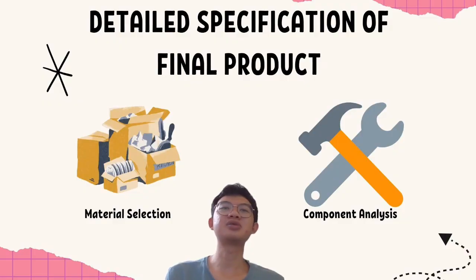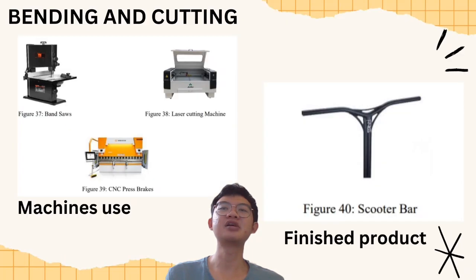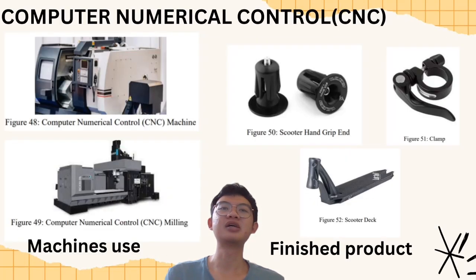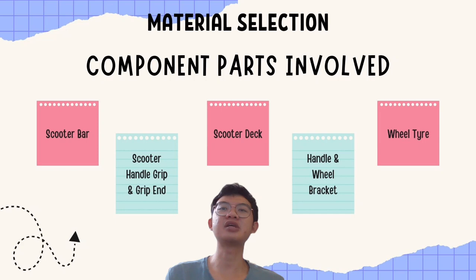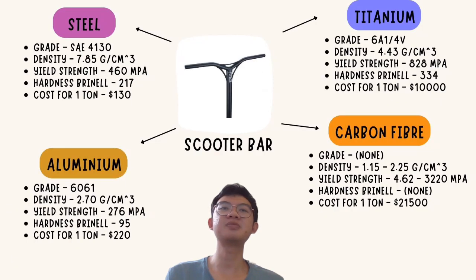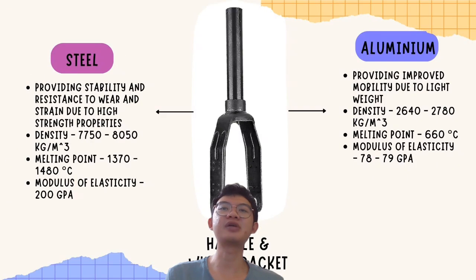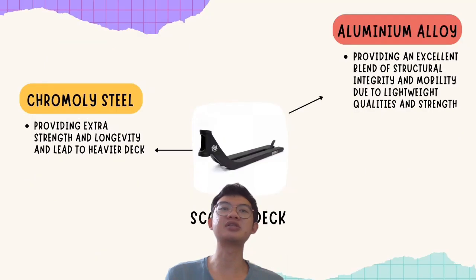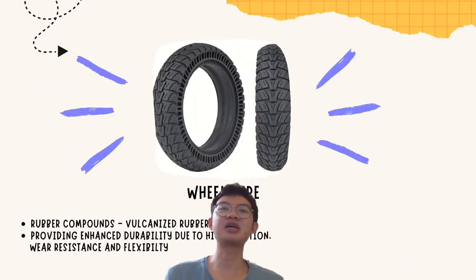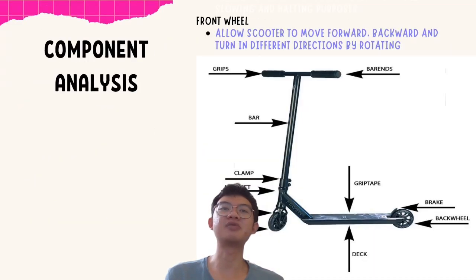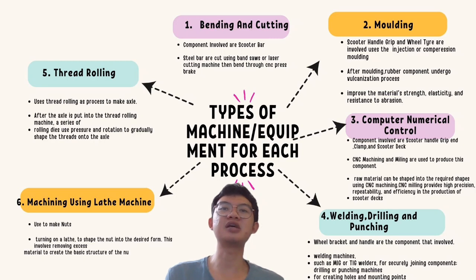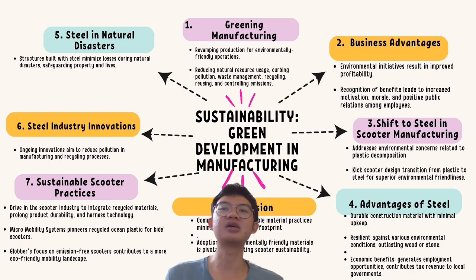In conclusion, kick scooter production involves material selection, cutting, shaping, welding, and surface treatments. Crucial material selection for modern kick scooters includes steel, aluminium, titanium, carbon fiber, and polymers for high-quality, user-friendly, and durable scooters. Advanced manufacturing techniques and ergonomic design enhance performance and longevity. Adherence to safety standards ensures a high-quality final product.